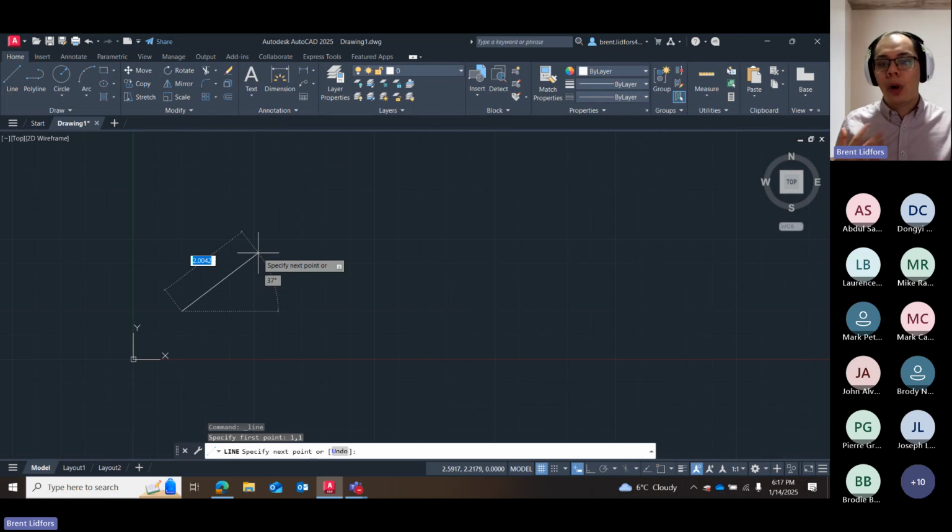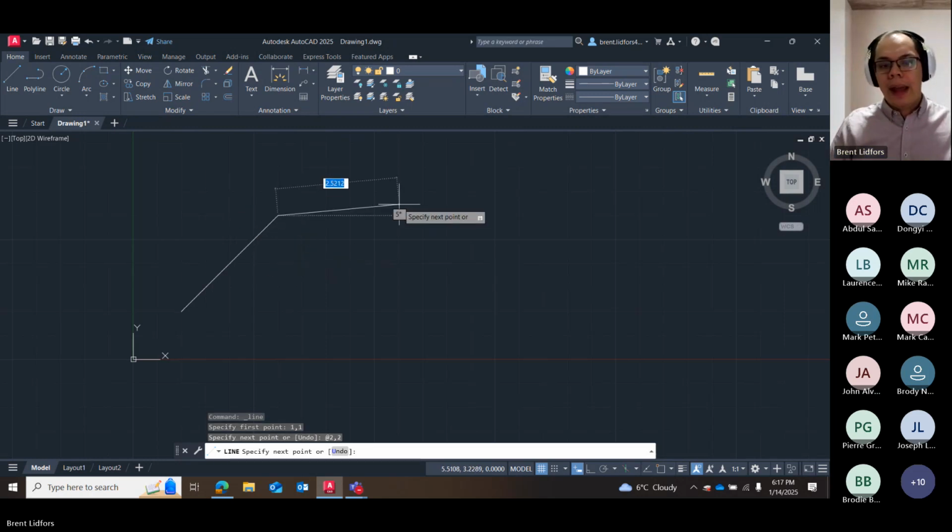What I can do here is also force it to be coordinates. So it doesn't have to be a length and an angle. If I type something like 2 and then press comma again, it switches me back to the coordinate system. And I can hit 2 again, hit Enter, and now it's drawn that line over to 2, 2 on that coordinate system.